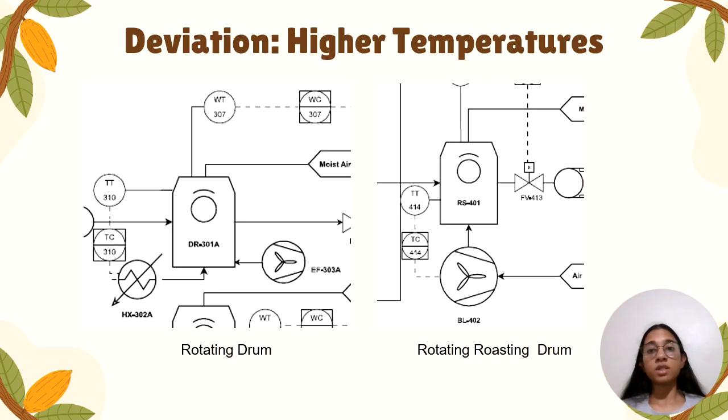Safeguards include installing low selector selective control, override temperature control in the control loops, safety interlocks to trip heaters if exceeding set temperatures, and critical priority alarms to command immediate operator actions to maintain safety.